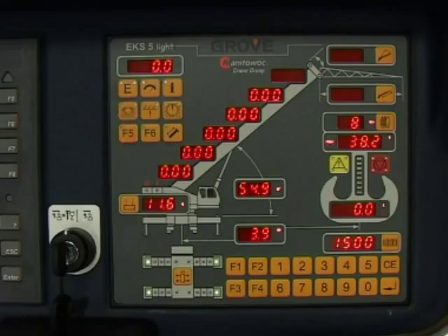crane operation. If the displayed reeving or RCI operating code does not correspond to the current operating configuration, you must enter the reeving or RCI operating code input modes to re-enter the required values.